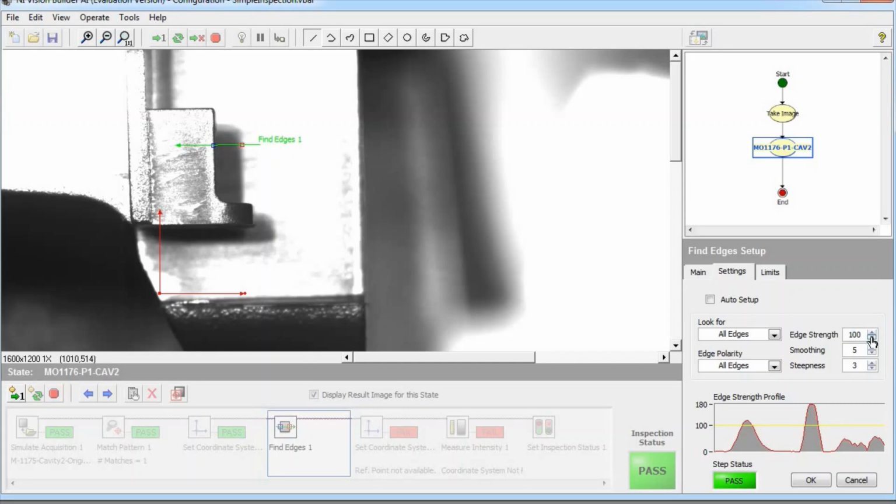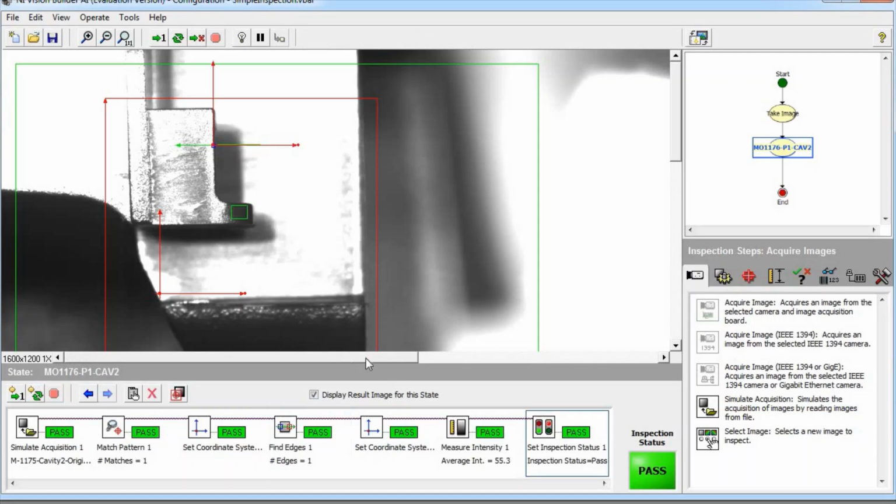So let's reduce that strength. If it is 100, that's too small because it will intersect on the shadow, so we have to increase that. Okay, 130, 140, 150, that works. Actually, we have a lower peak, which is the shadow, and a high peak, which is on the stronger intersection here. So we need to place the strength control somewhere in the middle between these two peaks. Then we click on OK, and the problem is solved.